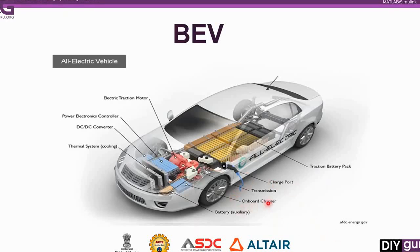So you will have an onboard charger for this one. And then you have a transmission, in case of a single speed or two speed transmission. Depending on the application, usually electric vehicles don't require any transmission, because they have very decent power characteristics. But in case you want to increase the torque, or you want to go to higher speeds, then you may need some gears. So you have a transmission setup for this.